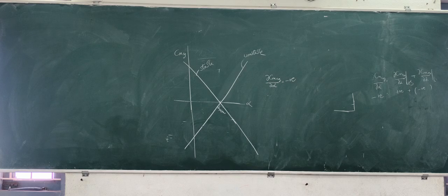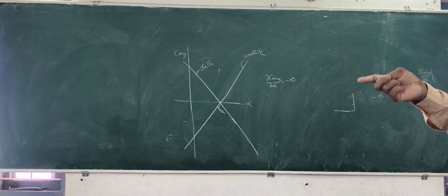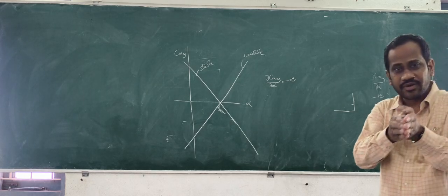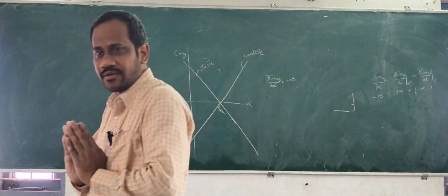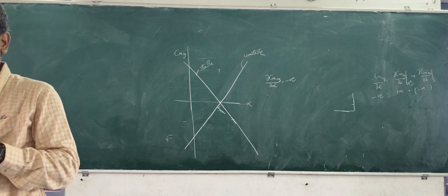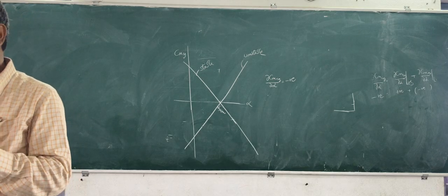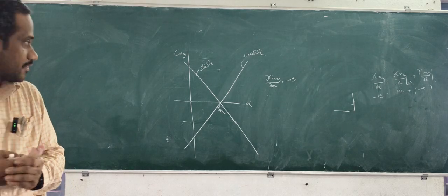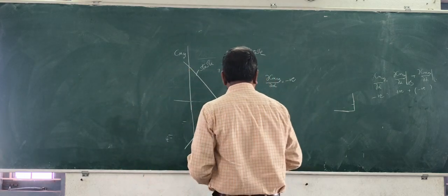If it is becoming positive, how much value do you need? Choose the parameters accordingly. Finally, the whole dou CM will become negative depending on the parameter selection: distances, planform area, tail setting angle, selection of aerofoil. All of them should together make this negative. The wing anyway is contributing in a destabilizing manner because of the inability to position the center of gravity ahead of the aerodynamic center. That is why the purpose of the tail came into the picture.